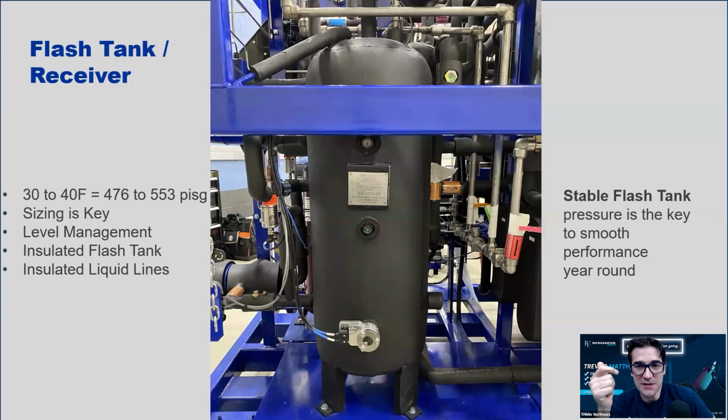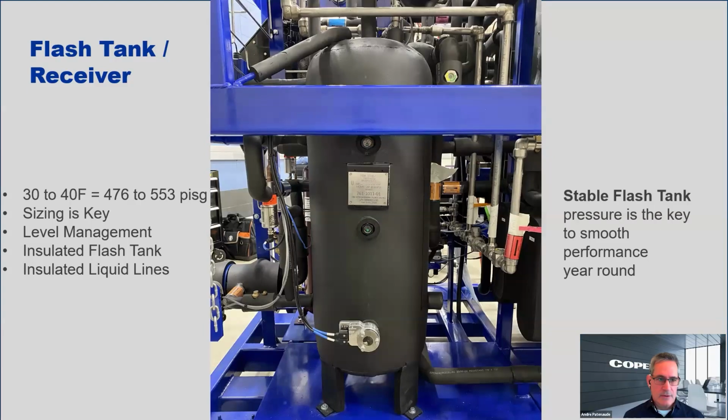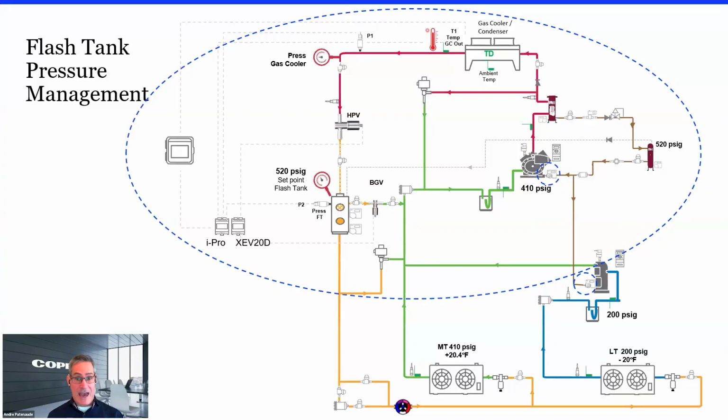Hot gas defrost, or it could be going back in there on return. There's so many. So you can imagine when you're looking at a flash tank that has all of this vapor coming in, vapor coming out, something else to really be aware of is that a lot of these oil systems will pressure equalize to your flash tank.